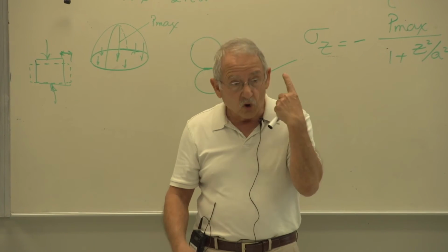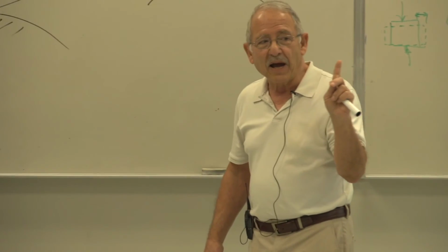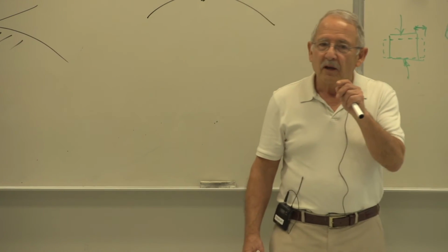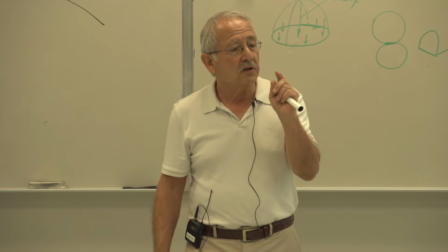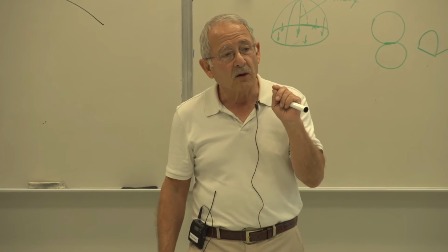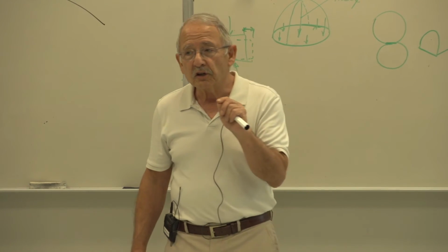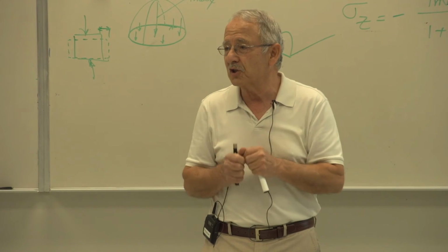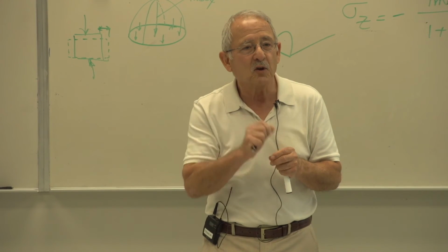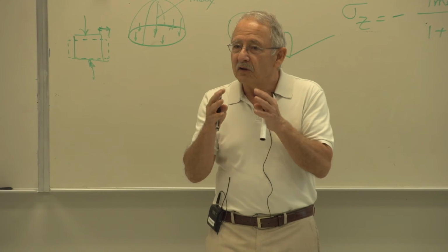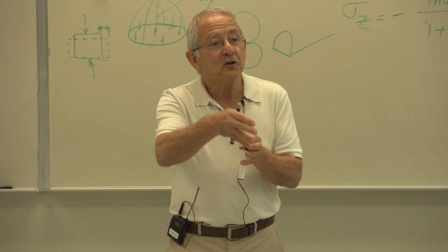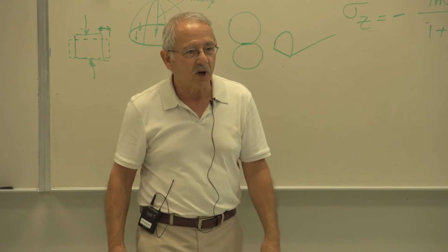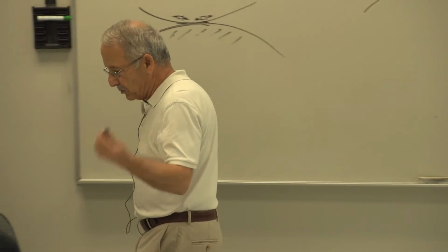Where that comes from, more often than not, one, of course, is bad and shoddy work. Put that aside, assume it doesn't exist, which it does. In most areas where that occurs, the temperature goes down in the wintertime and there's freezing. Inherently, concrete, when it sets, it shrinks. It would like to shrink. And most of the time, since you got steel in there, it can't shrink. So minute cracks develop on the surface. When the ice or snow on the road thaws, it enters these minute cracks. When it freezes, it expands and makes the cracks larger and larger, and that's what you get, those potholes. Aside from the fact that, of course, sometimes the work is shoddy. But that's one of the reasons you get those.